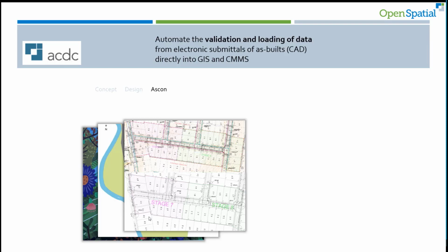And the reason we do that is because you need to be consistent, or you cannot validate and convert data if you get multiple formats and structures and layouts and everything else within that, particularly about the data. If data is just text next to a line in CAD, that's a problem. If it's on a call out or if it's attributes in a block, all of those make a huge difference to what you can do with it.